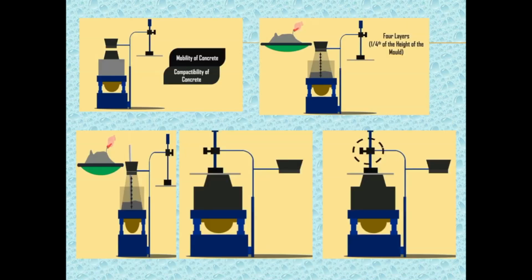Place the slump cone inside the cylinder. Now fill the concrete in 4 layers with each layer as 1/4 of the cone height and tamper the surface 25 times. Once filled, strike off the excess concrete. Move the glass disc attached to the swivel arm and place it on the slump cone such that it touches the concrete level. Note down the reading in the graduated rod.